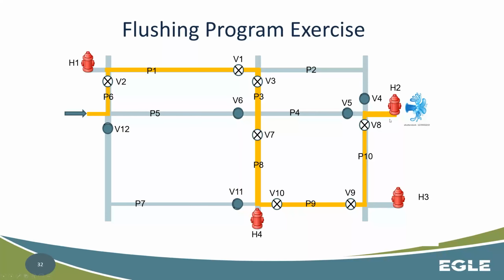And how fast are we flowing, so that we know how long we need to do this flushing to get material that is maybe associated with this main out that hydrant. Okay, so there's a little bit of math, a little bit of thinking to do here, but it's not the end of the day. It's fairly straightforward. Once you know the calculations, you know what you're doing, you can get there pretty easy.